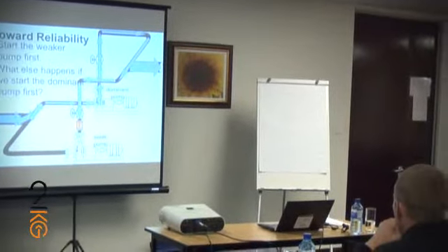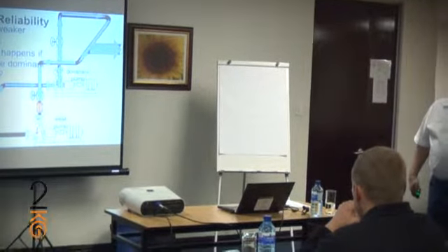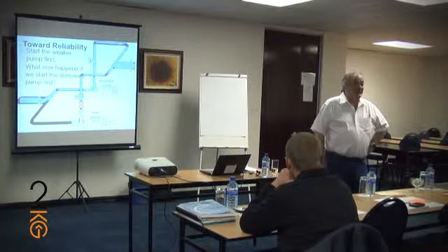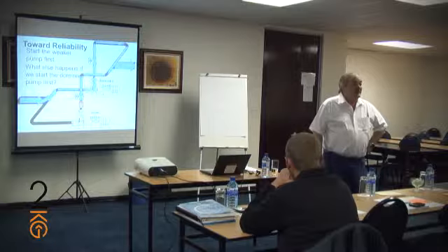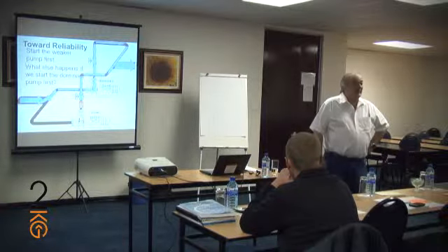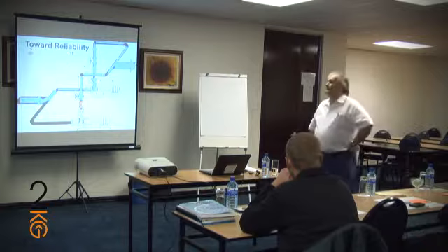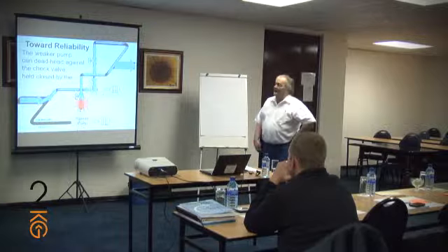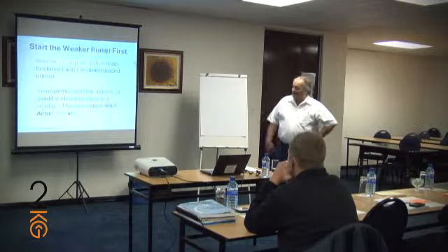So after this pump deadheads for 3 or 4 weeks, the seals and the bearings will fail from vibrations and distortion, and this pump becomes a high maintenance pump. And then somebody says, send those mechanics to a pump rebuild class so that they'll learn how to rebuild their pumps properly. The weaker pump can deadhead against the check valve right there, held closed by the dominant pump.